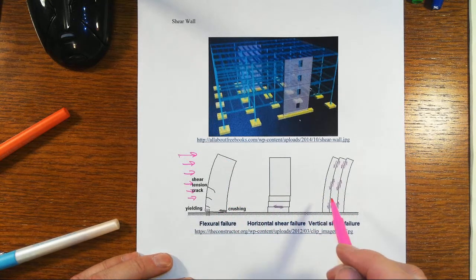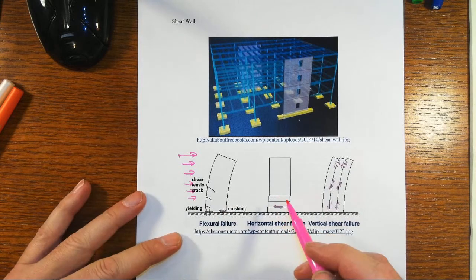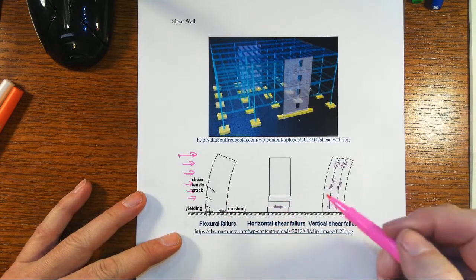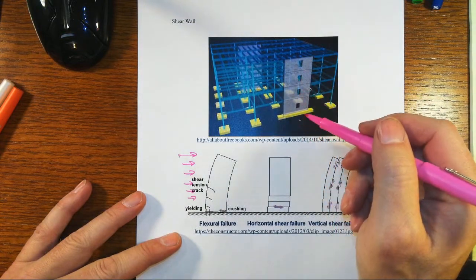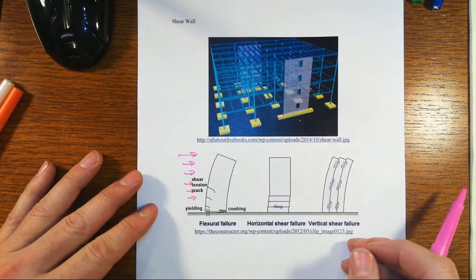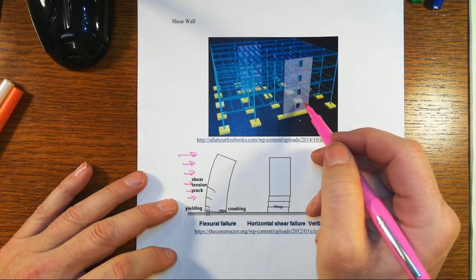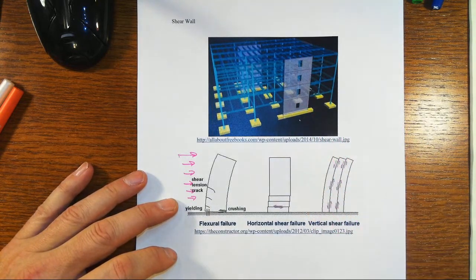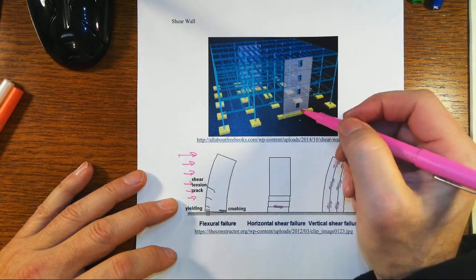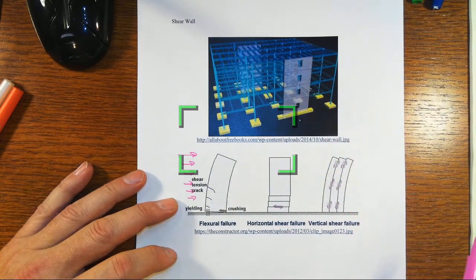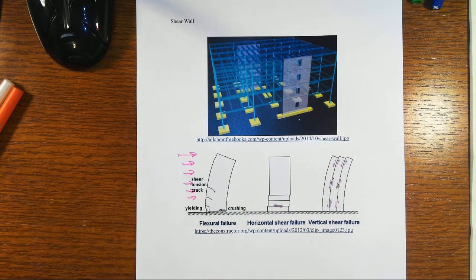You will tend to see these in tall buildings where they like to use the elevator core and the stairwell core also for shear walls. One disadvantage of shear wall systems is, of course, that you have a big solid piece on the outside of the building, and if you want to have a lot of window spaces, that doesn't work out so well. So that's why you would also tend to want to use these areas around stairwells or elevator cores to sort of use double usage there, to use as shear wall type systems. And yes, these holes in the walls do have a major impact on how that wall may perform, and that has to be accounted for in the design of that shear wall system.